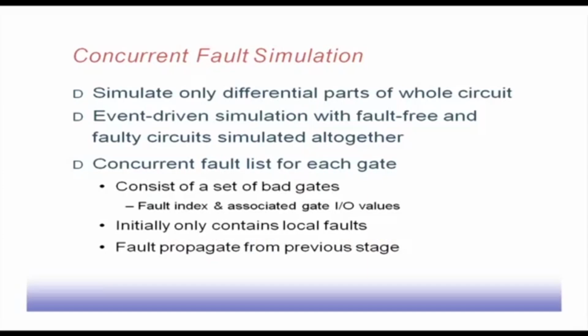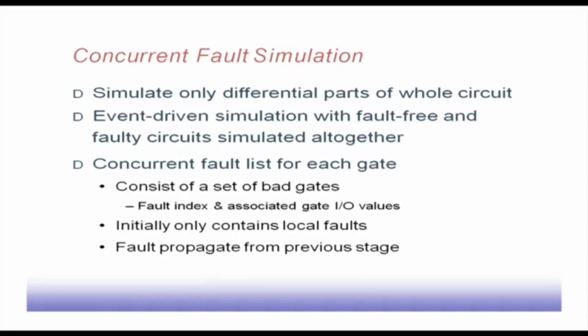So, it is an event driven simulation with the fault free and faulty circuits simulated all together. Event driven simulation means that if some part of the circuit changes, then only the output of that gate will be simulated. It is also concurrent, because the fault free and faulty circuits will be simulated together. So, it combines the advantages of parallel simulation and event driven simulation policies.